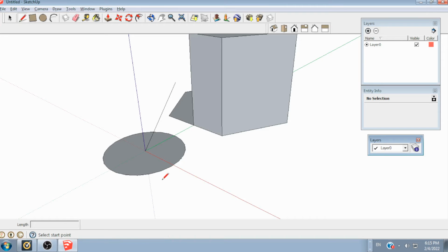If I hit the L command and go to the radius of a circle, and then drag, it'll find the center of the circle. Now, let me draw a circle over here, just not on an axis. So, where's the center of that? You can draw lines, the intersection, and that kind of stuff, but I just hit the L, hover over the outside edge for a second or so, and then move it in this way, it pops to the center.